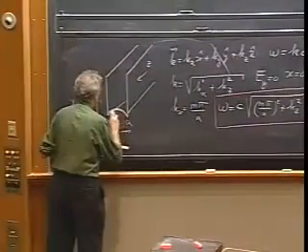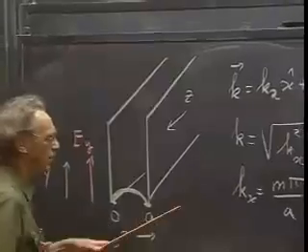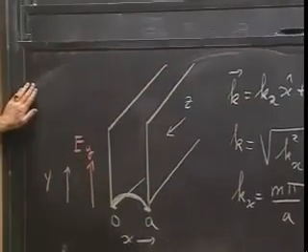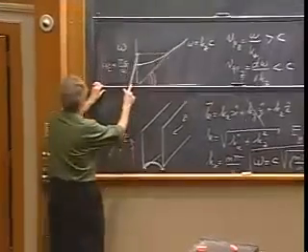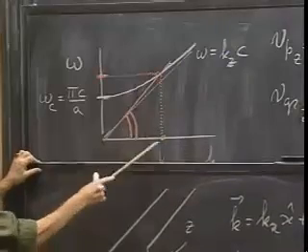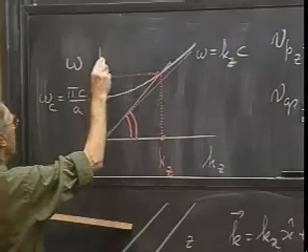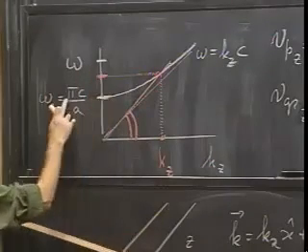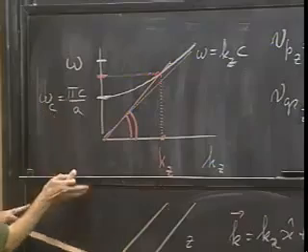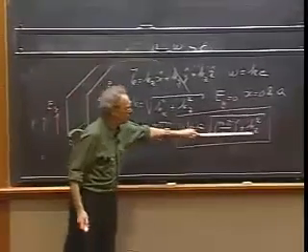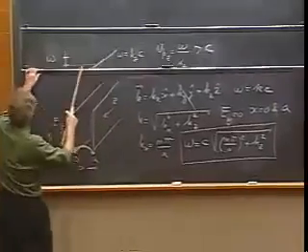Nice little sinusoid, 0 here and 0 here. That's for m equals 1. And kz will then be whatever it has to be. And so when you change omega, kz will adjust all the time. If you go to very high frequencies, there is another cutoff frequency, which is twice this number, because that is when m equals 2 and kz becomes 0, which is twice as high.